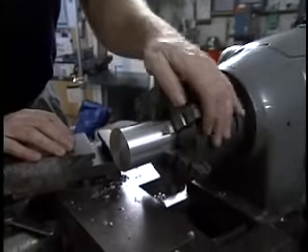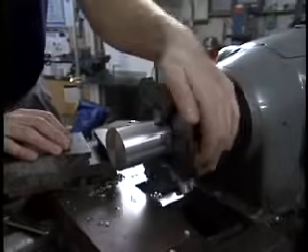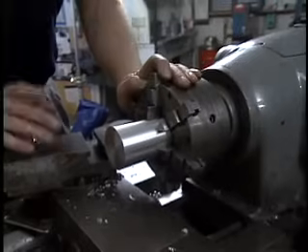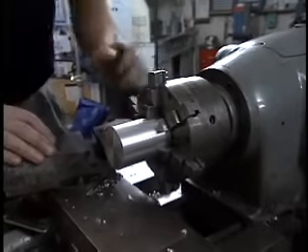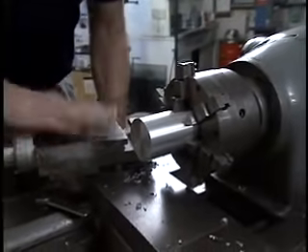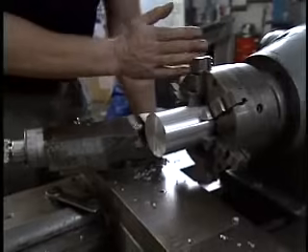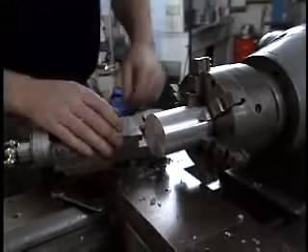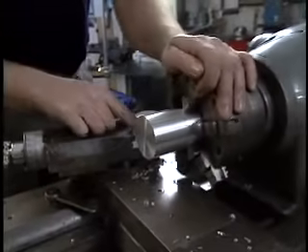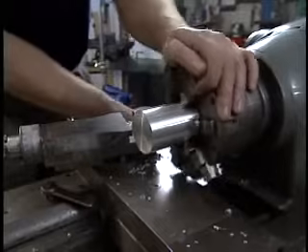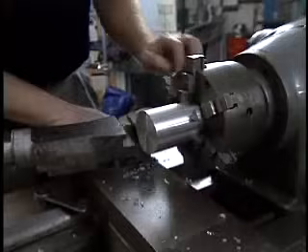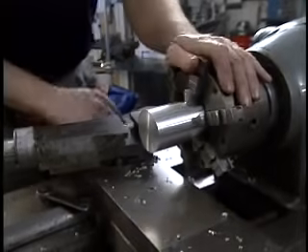Before turning the machine on, spin the chuck, making sure that there's no interference. In particular, this is very important when you're drilling, because often when you're drilling, you have the compound down very near the chuck. Make sure that you avoid this sort of interference between the jaws, the chuck, and parts of the lathe. Now it's safe to turn the machine on.